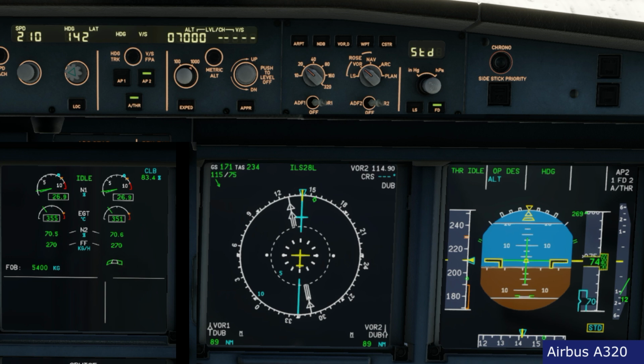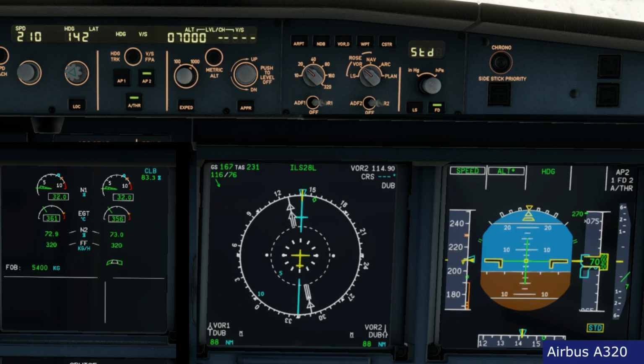In this different case, we see that the aircraft is descending in open descent. We're approaching the selected altitude of 7,000 feet. Of course, we see open descent, alt is blue, is armed, and as we reach the selected altitude, there we go, now we got altitude star, meaning that we are acquiring the altitude. Now we have the start of the phase where if I select a different altitude, I will revert into vertical speed. Finally, I get altitude green, so now the aircraft is maintaining the altitude, therefore I can change the selected altitude again. There will be no effect on the flight. I will remain on altitude green.